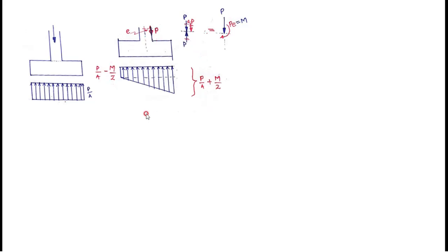Okay, this is the stress distribution. Here, whatever that E is, that E will come into the picture in M. Think that this load is eccentric from here, and think that this force is more away from the earlier one. If it is acting somewhat here, what happens? Then this stress will increase, and this stress may become 0. This reduces to 0, and this increases. Okay, that we can see here.